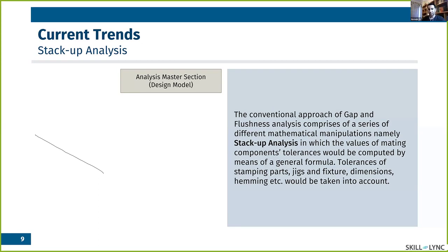I mean, for instance, the latch of the back door, and different hinges or fixings, and puts them there, considering that these aspects will affect the gap and flushes in the future. That person has the experience to know in which way these components and their designation will affect the gap and flushes in the future.